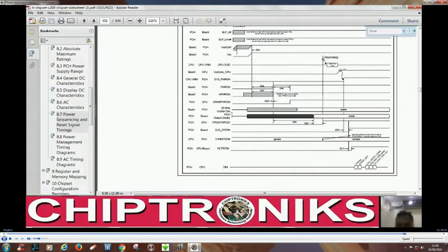Now, the core part of the CPU is turned on, that is, it has got supply. Second thing is that here it will get the crystal clock, BCLK P and N, right? The core part has got supply, and it has got clock also. From here, clock also.